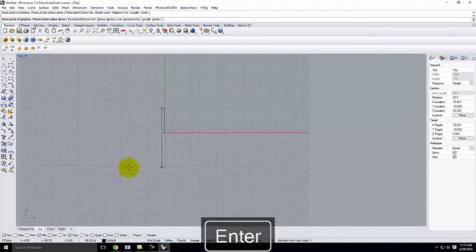over in this direction. Now, the next piece of this slopes out to the side, and because it slopes out to the side, I could do some math. I could figure out what the angle was. I could make a little guide that goes over 2 inches and down 36 inches, or I could use those relative coordinates that we talked about on that first day of two-dimensional drawing.